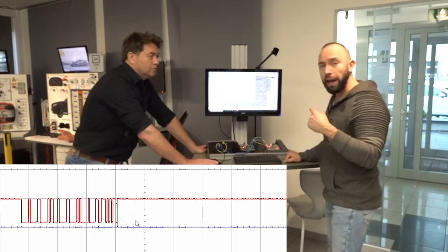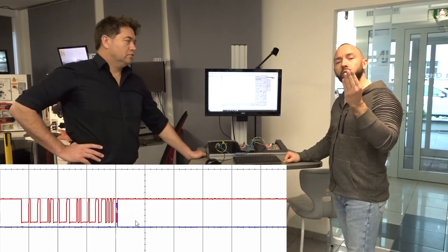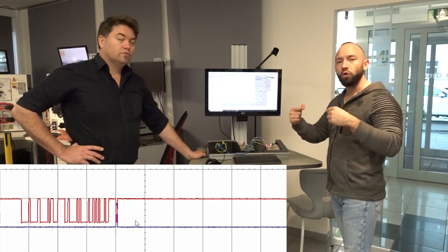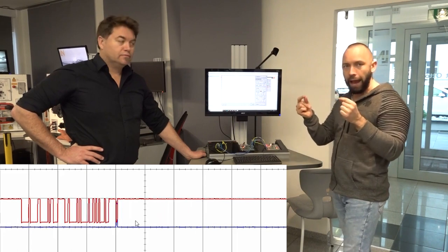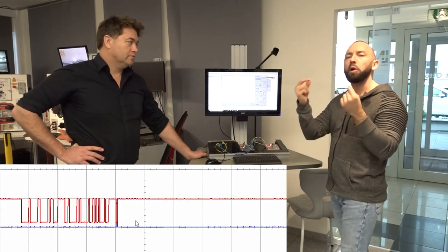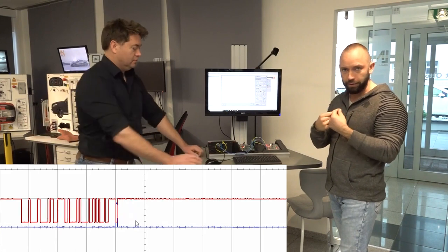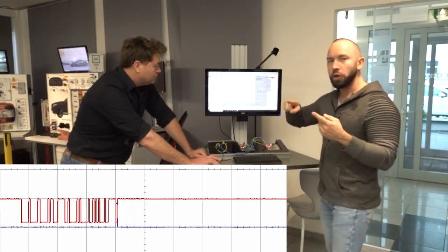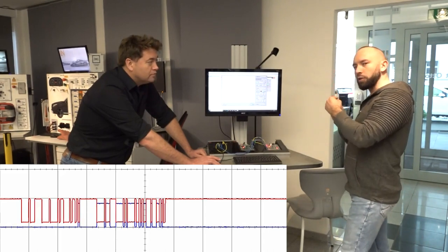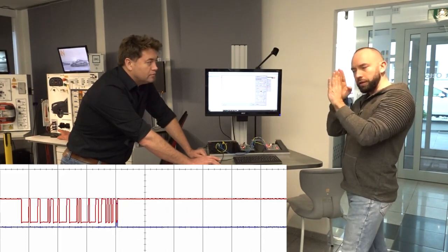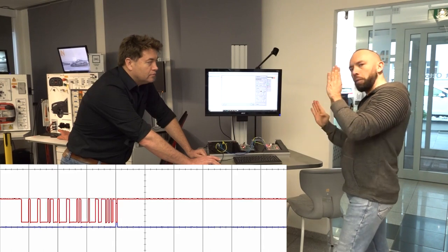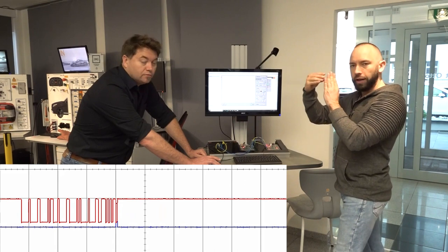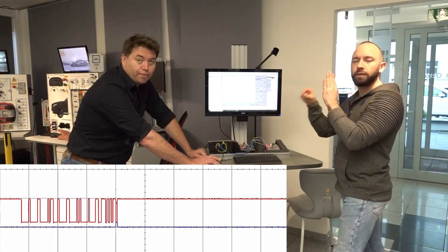So there you know with CAN low speed that the signal arrived at the CAN node, and the CAN node who got the signal then wrote the acknowledge bit on the channel. And it will write the acknowledge bit on both channels as soon as the message arrives. So when you see the acknowledge bit, you know that you're basically behind the interruption. The interruption is already done, and you measured now behind the interruption where the CAN node who got the signal on the other channel just sent the acknowledge bit.